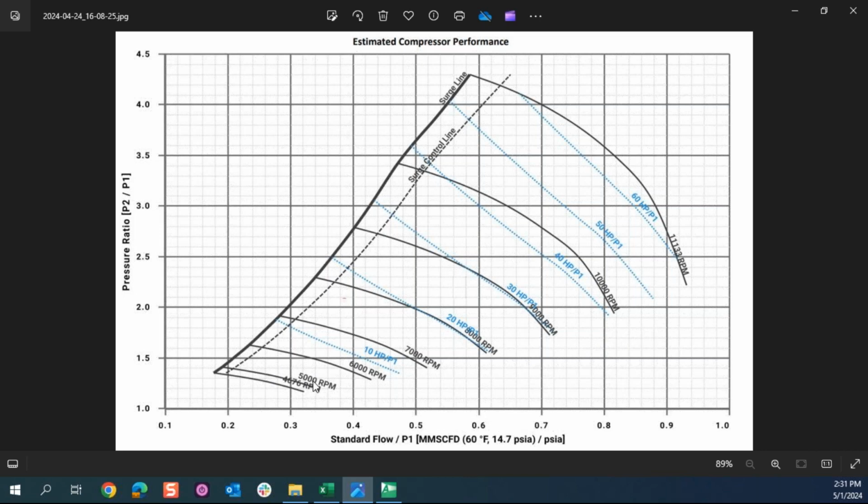And so we can see in our compressor map, we have pressure ratio on the left, which is good. That is what we saw earlier, how the software accepts the pressure side of this. If we come down here and look at the flow rate, we'll notice that we have standard flow over pressure, which is a little bit different than the corrected units that we were expecting.